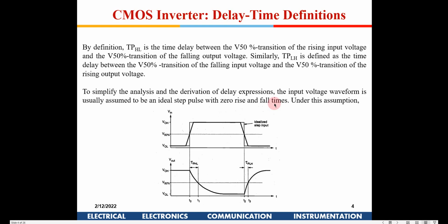So you have three different parameters now: NMOS slow, normal, and fast. Then you have three VDDs: nominal VDD, minus 10% and plus 10%. And the third thing is temperature, with three different temperatures including room temperature.